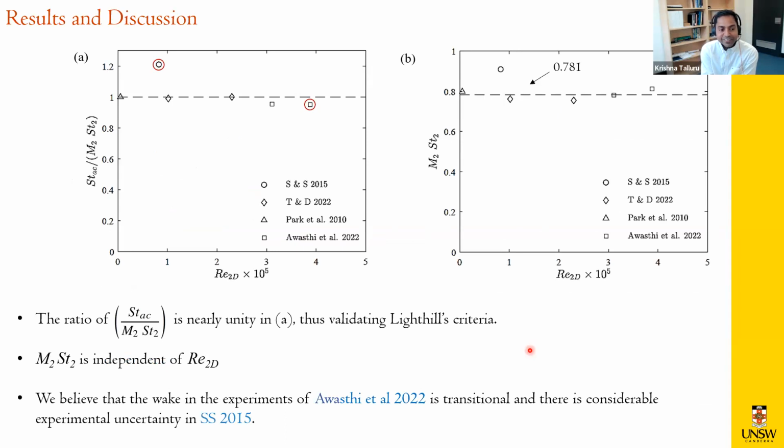Unfortunately, the reviewers did not accept it. And I'm still going to fight back. Yes, this is the point I really want to make. It is the post-shock conditions. The flow, or the boundary layer and the wake, will only have memory of what is happening downstream of the bow shock. It doesn't have the memory of the pre-shock conditions.